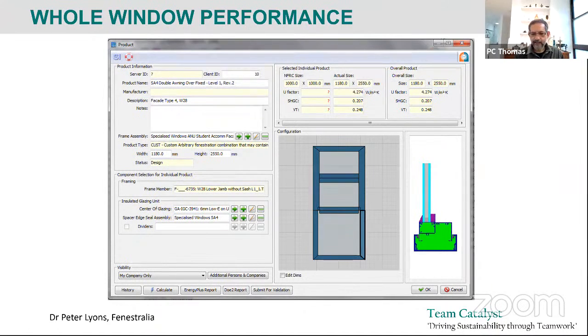Now, solar heat gain coefficient for the whole window is less difficult. You can find the fraction of the whole window, which is the frame fraction. So typically the frame area will be somewhere between 5% to 15%, unless it's a very residential thick frame type window, but you can work that percentage out.